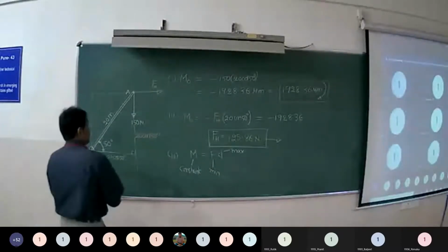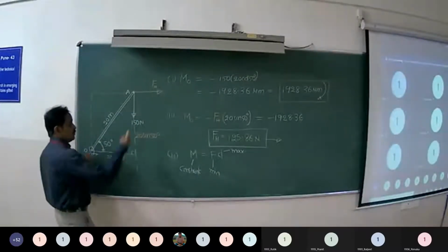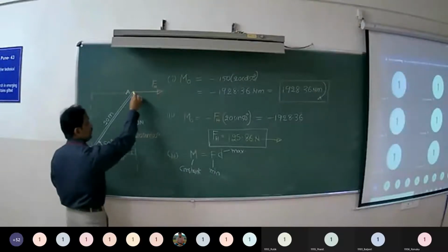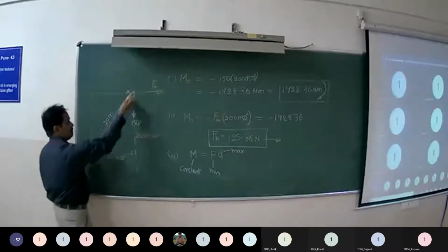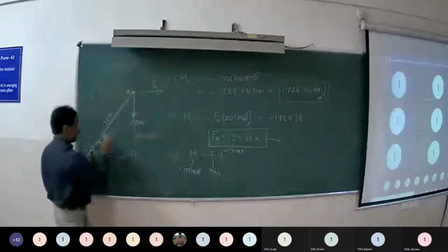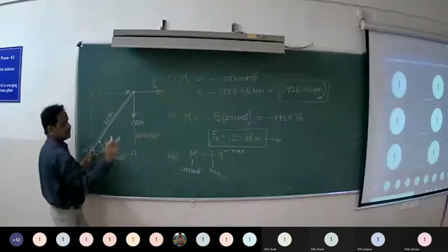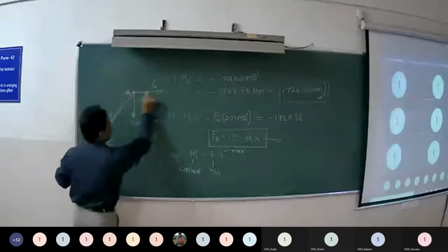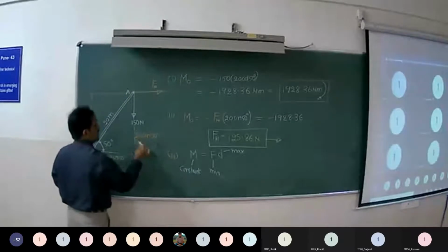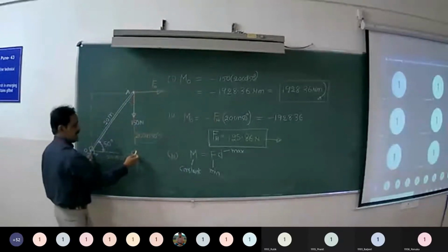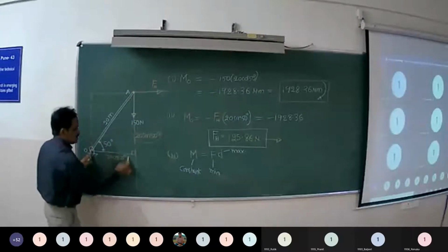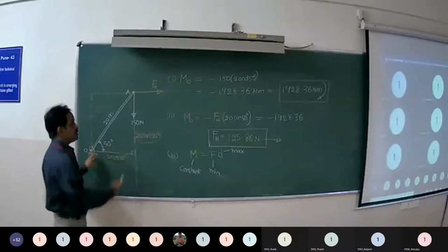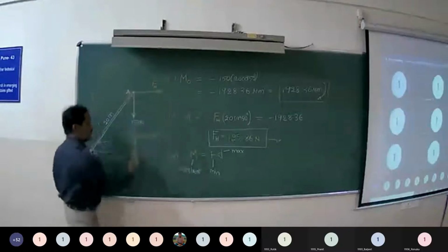Now, here you have to find out the direction of that force such that you will get a maximum perpendicular distance from the line of action of that force to this point O. Say, when the force is acting horizontally, 20 sin 50 is the perpendicular distance. When force is acting vertically, 20 cos 50 is the perpendicular distance. These are extreme cases, horizontal and vertical.